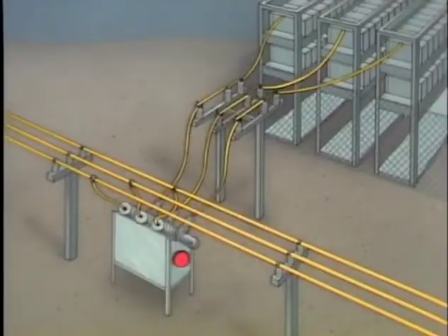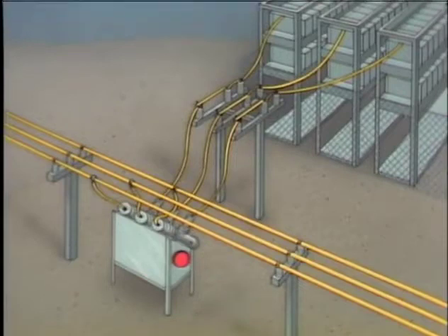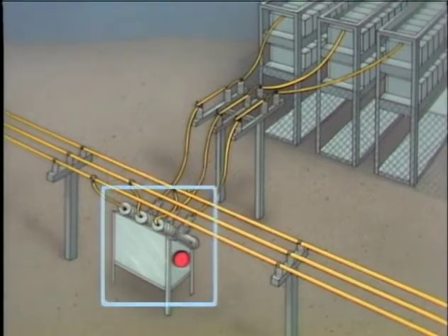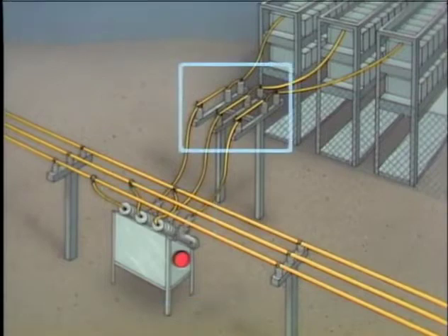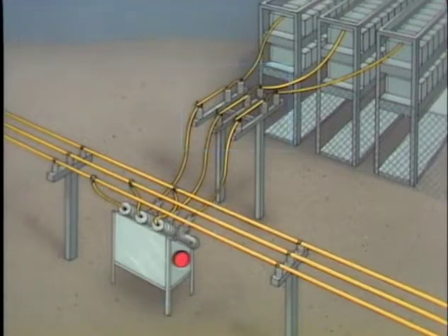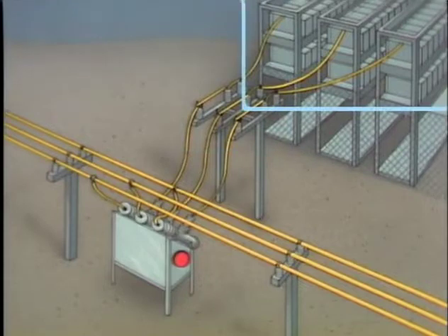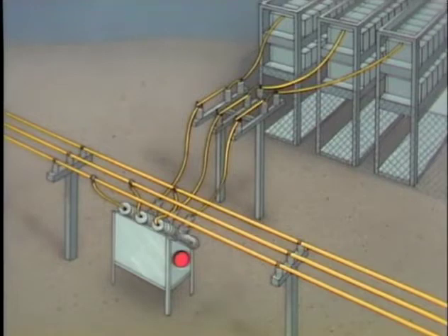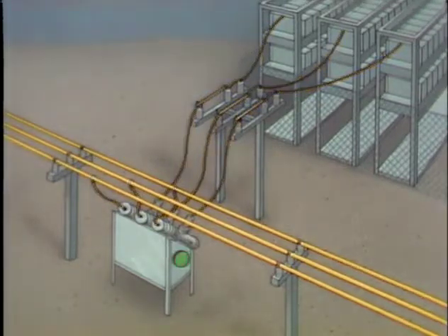This simplified illustration will help show the general principles of de-energizing and isolating a capacitor bank. The illustration includes an energized three-phase bus, a three-phase circuit breaker, 3 single-phase disconnect switches, and a three-phase capacitor bank. Very simply, a capacitor bank is de-energized by electrically separating the bank from its source of energy. In this example, the bank is de-energized by opening the circuit breaker. A capacitor bank is isolated by physically separating the bank from its source of energy.